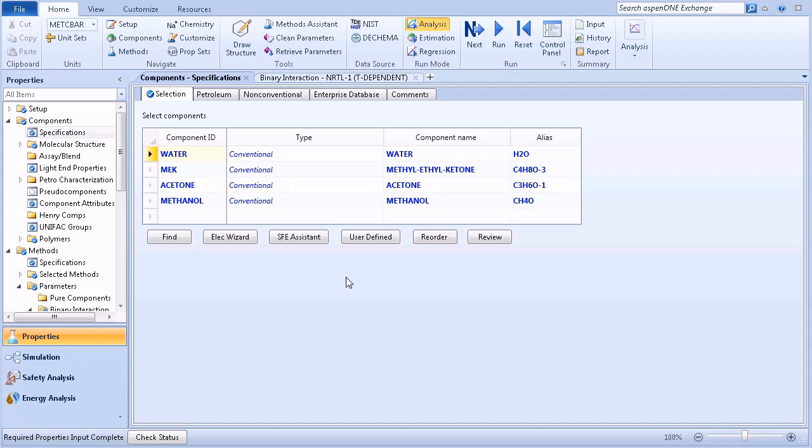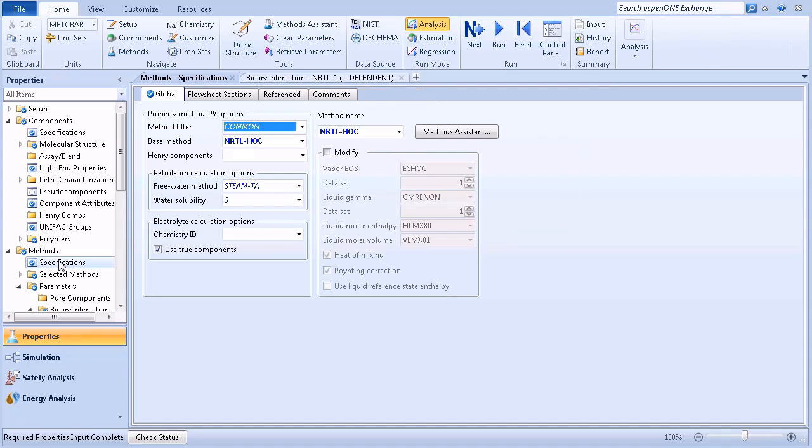This demo investigates the separation possibilities for an acetone-water MEK mixture using ternary maps. The file has four predefined components: acetone, water, MEK, and methanol, and a selected property method of NRTL-HOC for the analysis. We assume that binary parameters and data are good and well represented in this system. First, we will evaluate binary azeotropes using binary analysis.